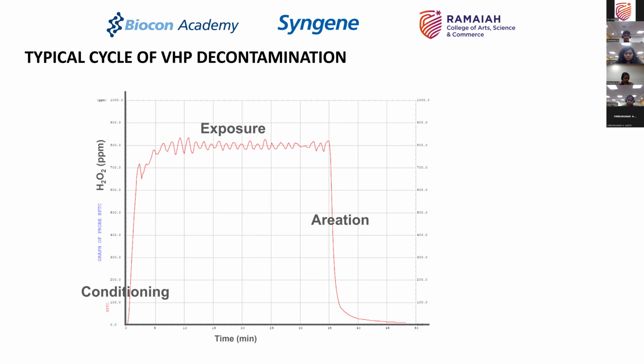Always remember that in any pharmaceutical application, whenever you specify a parameter, temperature, pressure, dosage of H2O2, dosage of gamma irradiation, temperature for sterilization, you always have to specify it as a range. Even the temperature of your room is never a singular value. It is always 23 plus or minus 2 or 24 plus or minus 2. Humidity is always a range. The regulators are looking at the higher and the lower limit defined around the central point that you have determined for everything. So it is never a constant value.